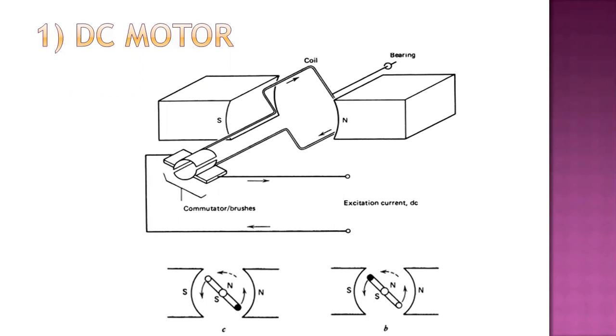Actually, the armature current is not determined by the coil resistance because of a counter EMF which is produced by the rotating wire in a magnetic field. Thus, the effective voltage which determines the current from the wire resistance and Ohm's law is the difference between the applied voltage and the counter EMF produced by the rotation.